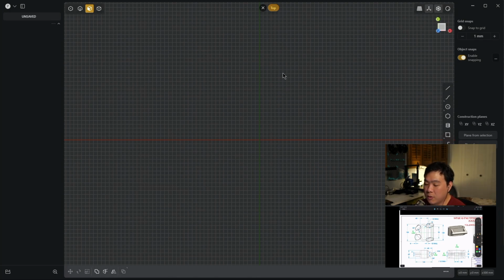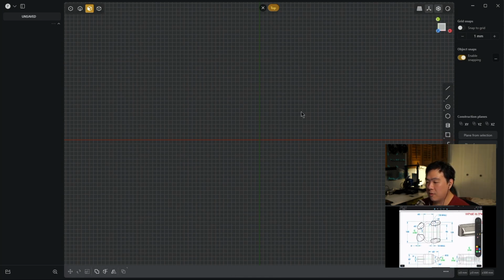What I'm going to do is first create that outer oval or ellipse shape. What we're given in the diagram is the width of the outer ellipse, which is 60 millimeters. That also happens to be the diameter of the arc over there. In order to model that, we're going to use the center circle tool. We can access it on the right-hand side, but on my Windows machine it's Alt-Shift-C, so that's what I'm going to press. I'm going to snap along this Y-axis, click anywhere, press Tab, enter 60, and press Enter twice to confirm.